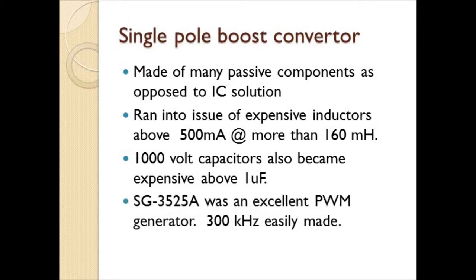Finally, we came across the SG3525A PWM generator. This is an excellent choice to generate our switching signal, as it has a switching frequency range from 60 kHz to 400 kHz and a duty ratio of 0 to 49% or 51 to 100%.